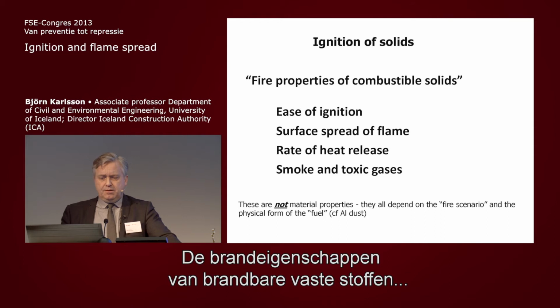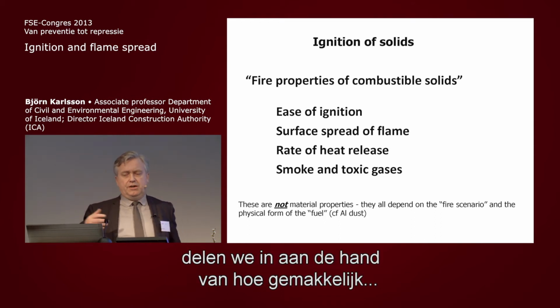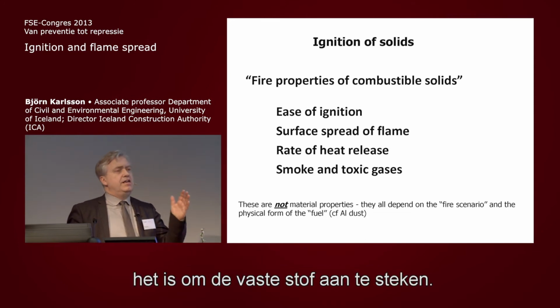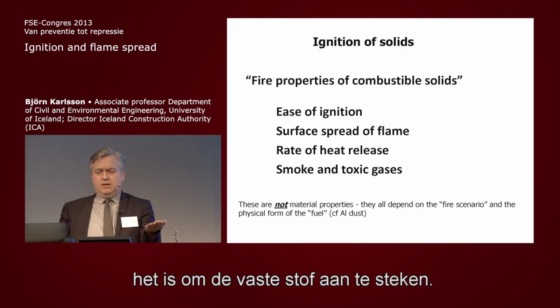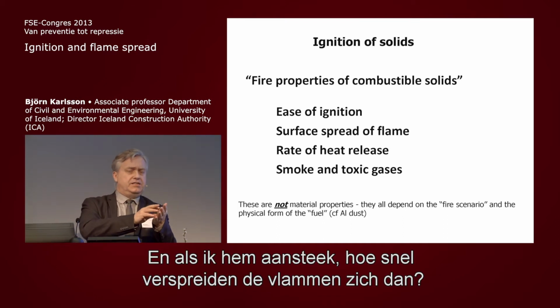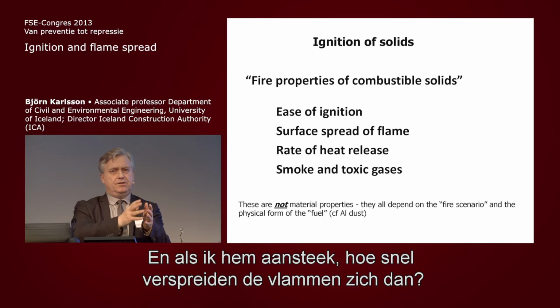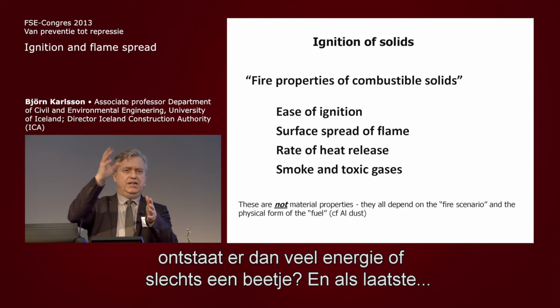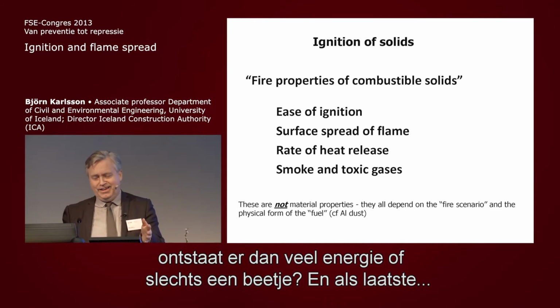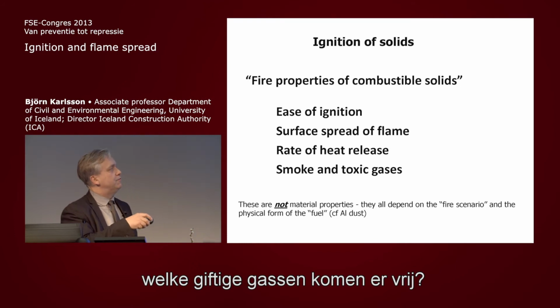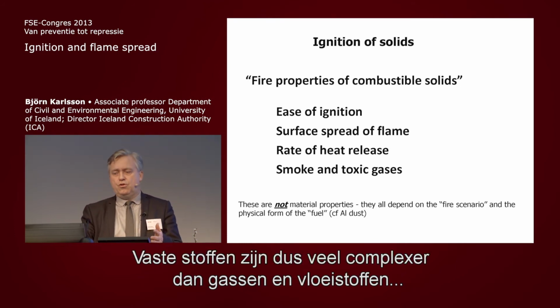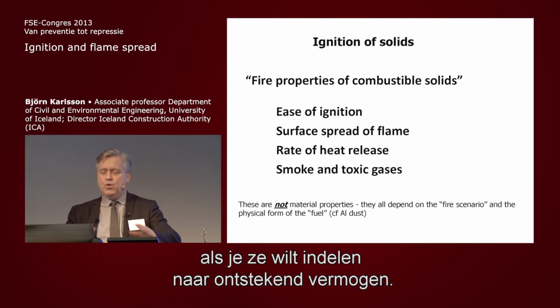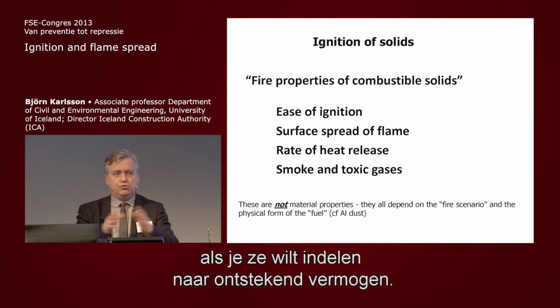So, the fire properties of a combustible solid is really how easy is it to ignite this solid? How easy is it? And when I ignite it, how quickly will it spread the flame? Those are the things I want to know. Also, when I've ignited it, will it give me a lot of energy or just a little bit? And finally, what kind of toxic gases will it produce? So solids are much more complicated than gases and liquids when it comes to trying to classify them according to ignition propensity.